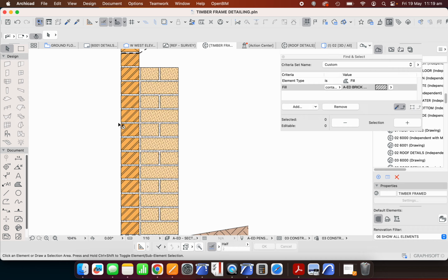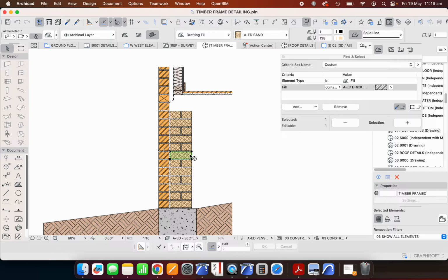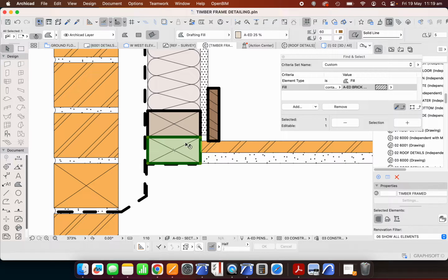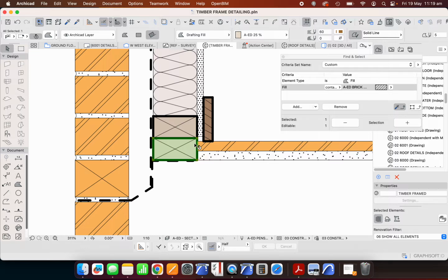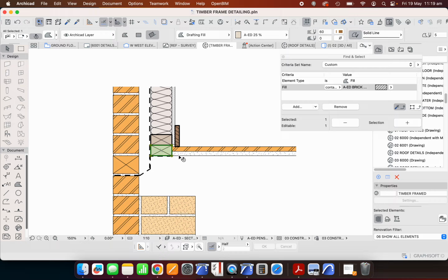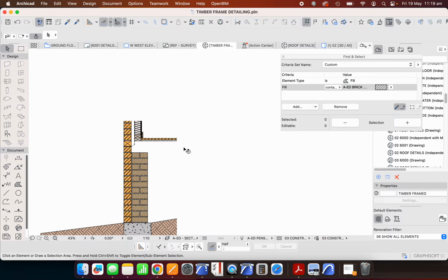All right, so now we've got our brick in section, our brick in elevation. This is our engaged pier. And now we need to start adding timber. We were using a structural piece of timber, or in this case, we're suggesting that it's pine, radiata pine, for our stud. For our bearers and joists, we're going to do something a little bit different.